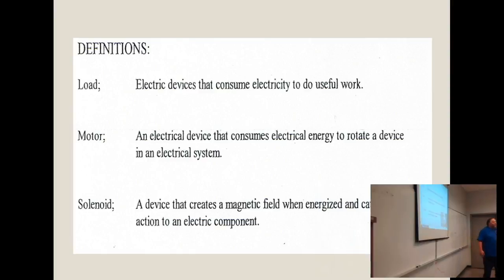Now, why would a sequencer use time delay? Okay, I'm going to tell y'all how. Because this can draw more power than anything in your house. This is 5 kW, about 18, 19 amps. Depending on the size of your house, you may have 4 of these. 20 kW, 80 amps. Now, some of these big fancy houses have a 200 amp circuit. That's almost half of theirs. Some of these other houses have 100, 80%.